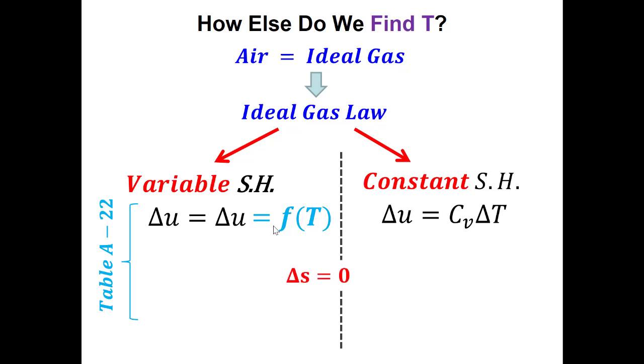Like I was saying though, when the working fluid is an ideal gas, the trick is identifying which of the processes are isentropic, or where delta S is equal to 0. And if you remember what the second law looks like, you're going to have that Q over T term, or Q dot over T term. And when that exists, delta S can never be 0.